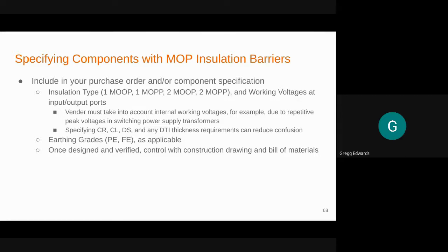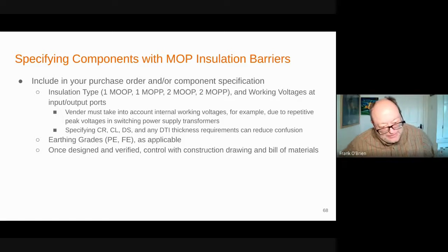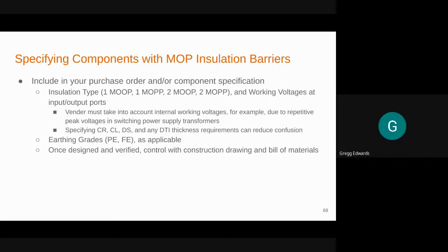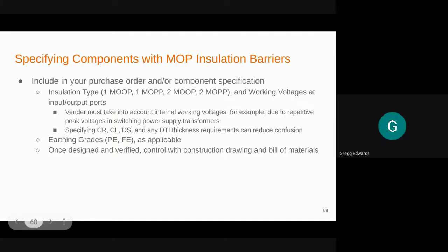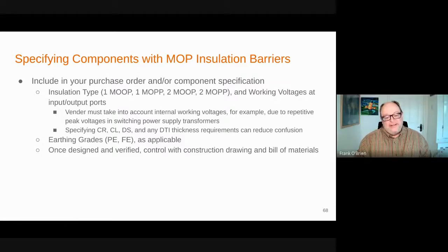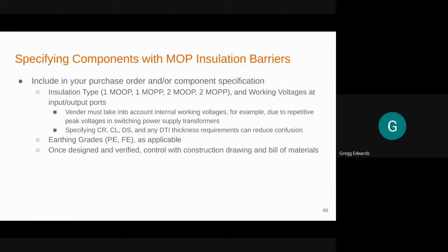Something for folks to be aware of is to try to design for multiple footprints going forward. It's related to all those chip shortages; I'm seeing it in a couple of different places. And then follow-up inspections could get tricky if they pick the right stuff. Yeah, a digital isolator or something of that nature.